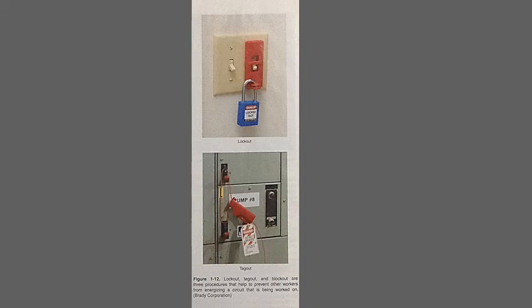If the equipment contacts the power lines, the electricity will flow through the equipment, through your body, and into the ground. Even if the equipment does not touch the power lines, it can come close enough to draw an arc. To reduce this risk, carry the equipment horizontally to avoid walking under the power lines.